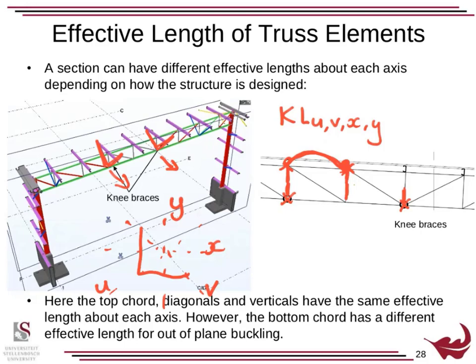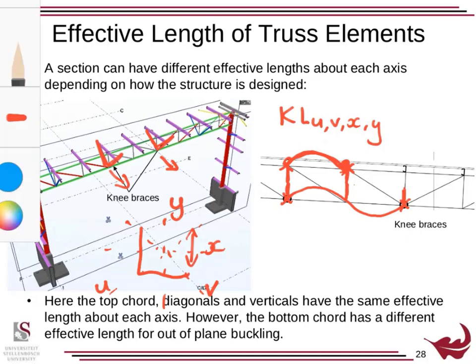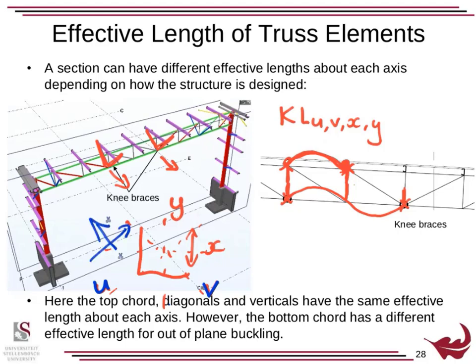So when it comes to buckling about X, that's can it buckle up or down, it would look like that if I was going to consider this. Same thing with U and V. If U and V were to experience buckling, I'm just going to change color just to hopefully make it clearer for you. U and V, the section would have to buckle both upwards and across to go diagonally up or down. So it would either have to go that way or that way to buckle about U or buckle about V. And so it can't go up, so it would follow the same shape. So it would buckle diagonally up or diagonally down to each side or the other.